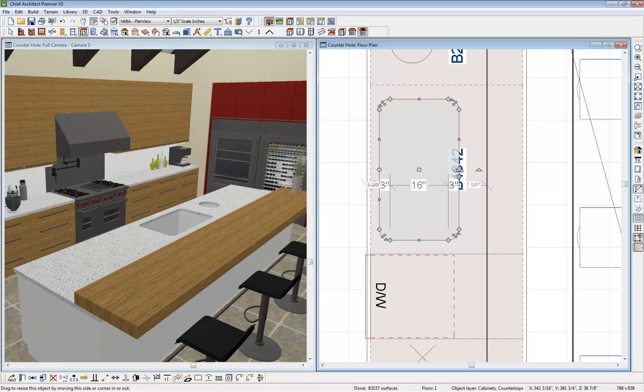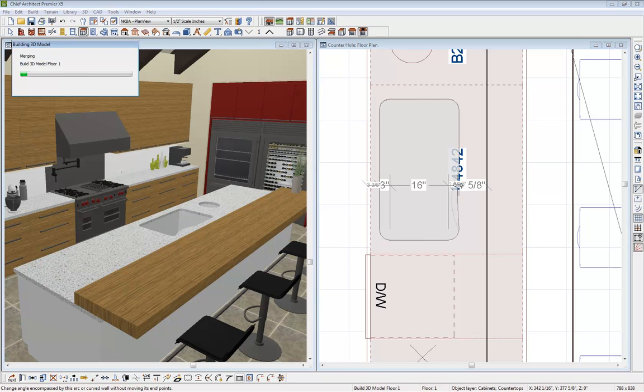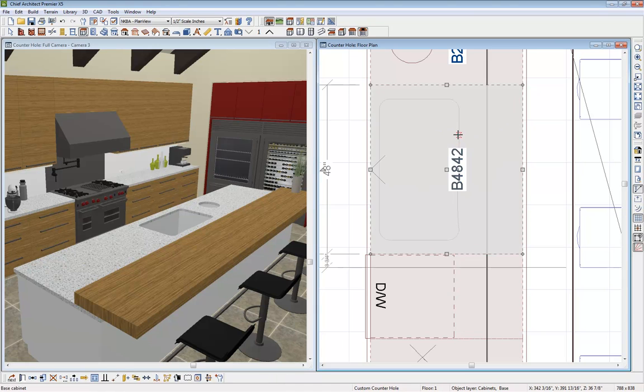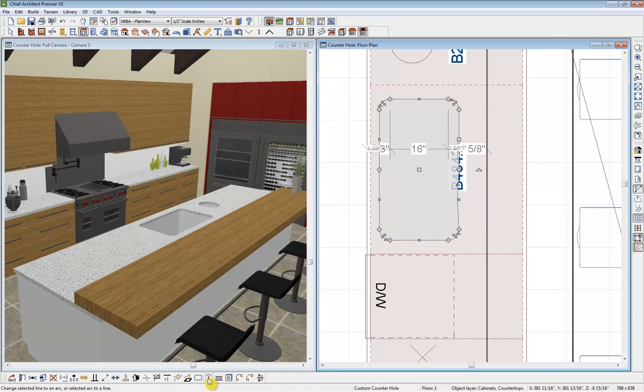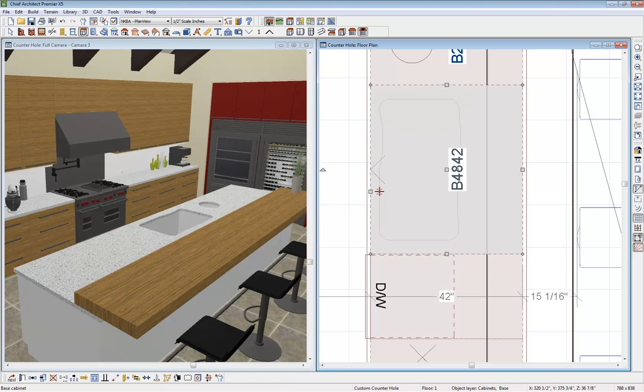And now let's make a curve on that. So I'll be using my change line arc tool down at the bottom. So with one click, it will change that, and then we can change that radius. Let's just bring it down a little bit and work our way around. So again, if you don't select the right object, just hit tab, and that's a very quick, easy way for you to select that edge again. Alright, so we're just going to work our way around just a little bit here. And maybe one more.